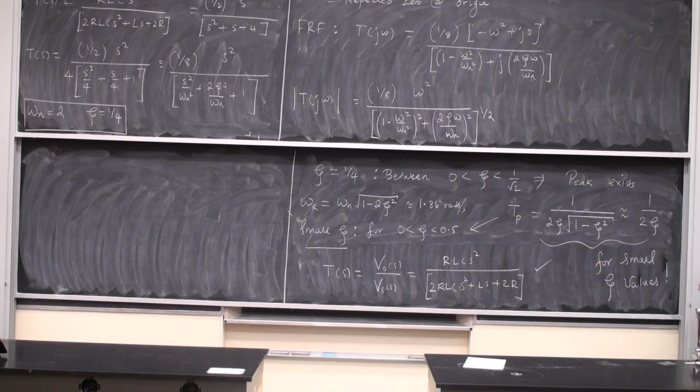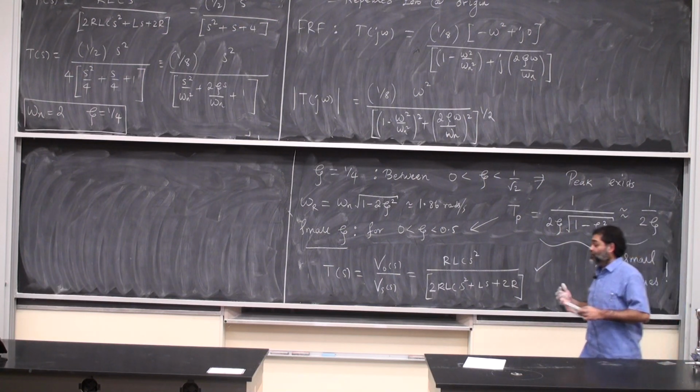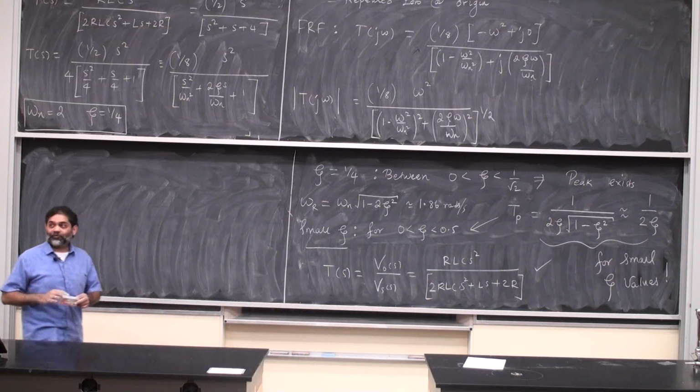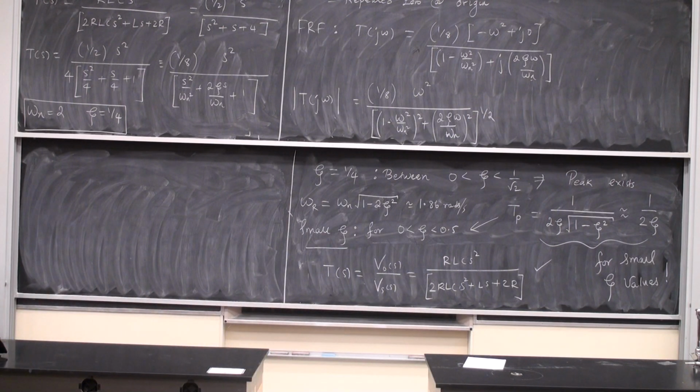You do it this way if you have an underdamped system. If you have an overdamped system, we looked at it in the last lecture, you write it in a slightly different form. You take out the zeros, the frequencies, you take out the poles, the roots, and so on, and then write it out. So here, I'm now going to go into the Bode plot regime.